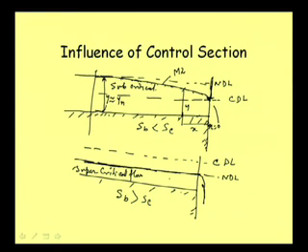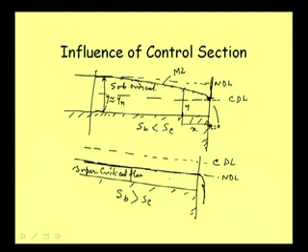So, that is how the knowledge of the control section is required. Generally, the feeling may come that whether it is supercritical flow or subcritical flow, it will be dropping like this, but no, only in subcritical flow it will be coming like this and dropping like this, but in supercritical flow this will go straight and then it will fall like this. So, this sort of understanding will be required while computing gradually varied flow, and of course, analyzing different situations under gradually varied flow.